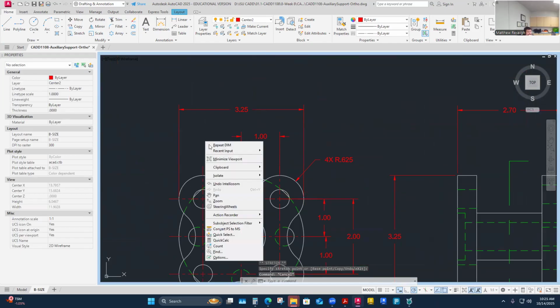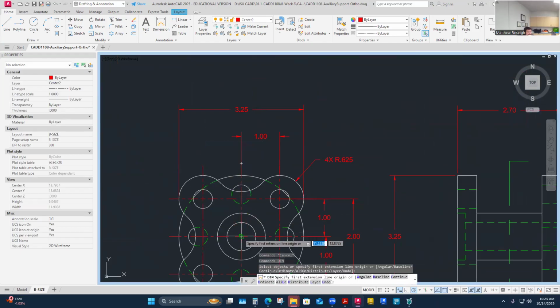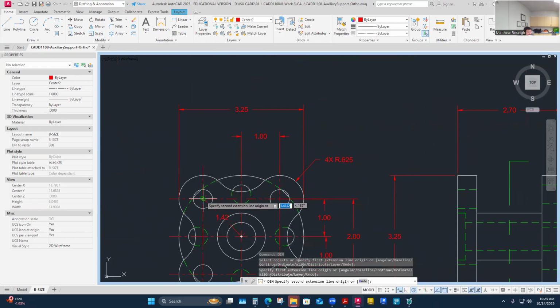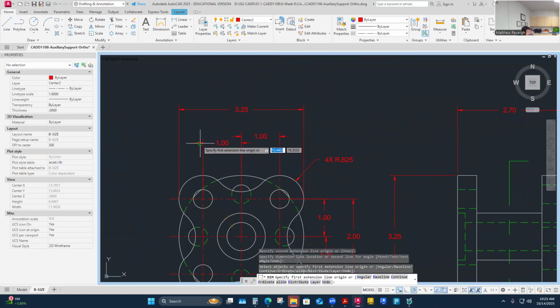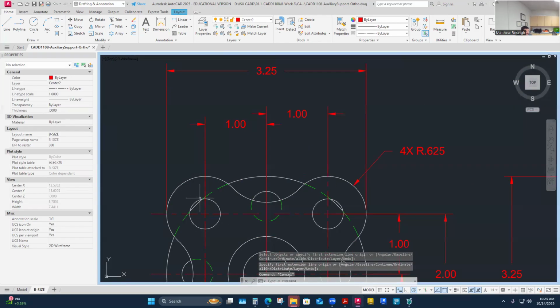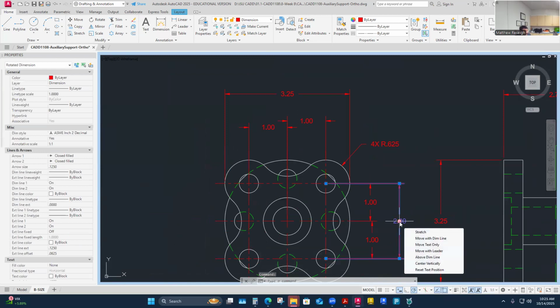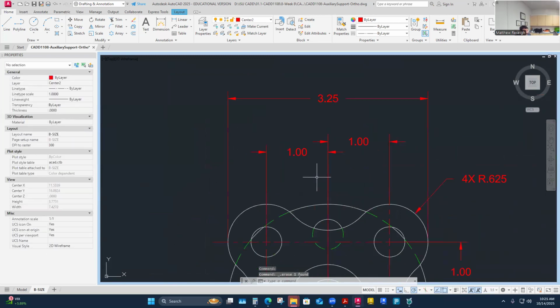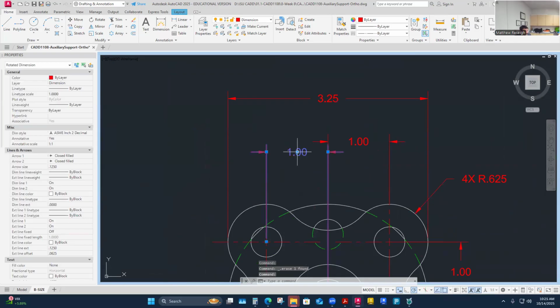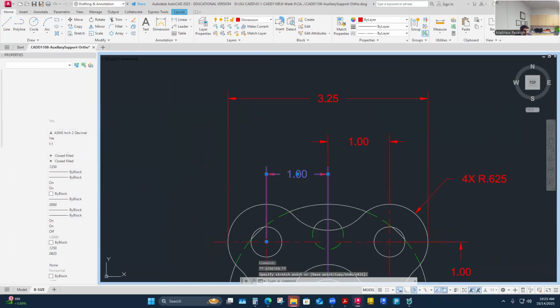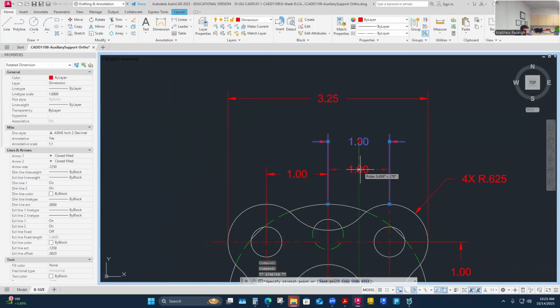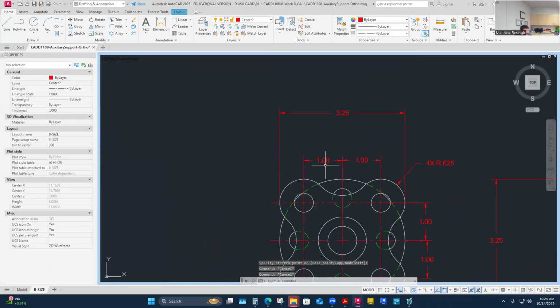And then I would do the other thing. I would do the same dimension this way here, right? From here to here. And if I add the 2, okay. If I don't, this is pretty easy math. I could maybe eliminate the 2. You know, I might argue that this is redundant. It's not a double dimension. It's just maybe redundancy that's obvious. If it's less obvious, leave it. And if one's a reference, that'll expose itself once we know the true nature of the part.